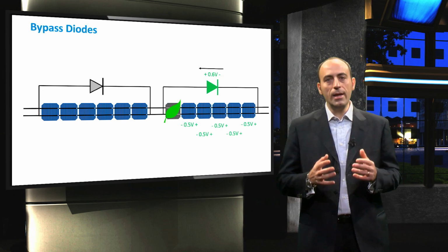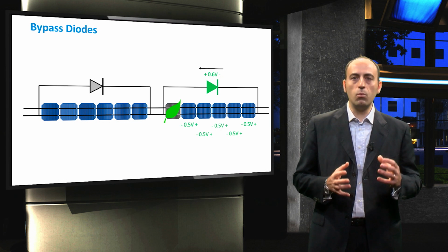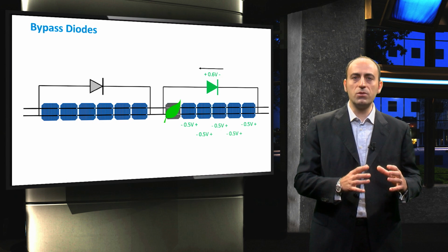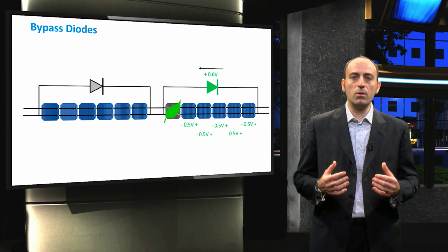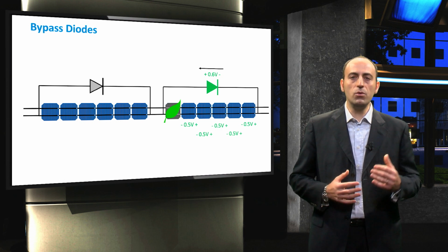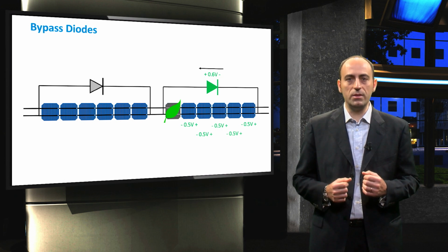Until now, we have seen series and parallel connection among cells within the module, but note that you can also have modules that are connected together in strings and then in arrays. So we have to project the same type of problems discussed at cell level to module level. Let's imagine a very large PV plant of hundreds of modules. It may happen that one part of the plant is partially shaded by clouds, while the other is still well illuminated. As a consequence, partial shading without bypass diodes generates a very huge imbalance that even for a few seconds can hinder the lifespan of the complete PV system.